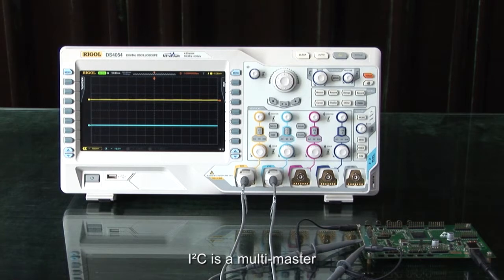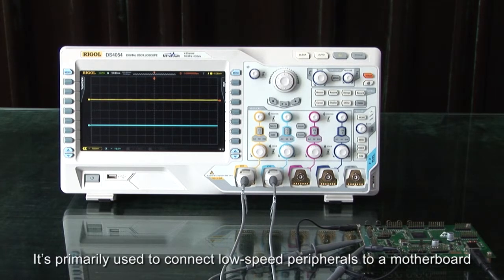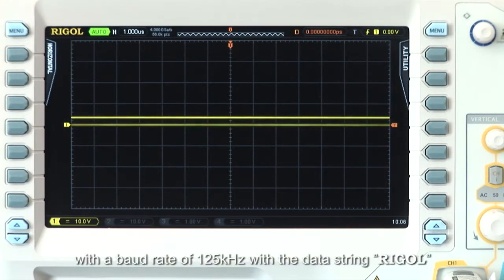I2C is a multi-master, single-ended serial communications bus invented by Philips. It's primarily used to connect low-speed peripherals to motherboards, embedded systems, cell phones, or other electronic devices. Here is an I2C signal with a baud rate of 125 kHz and the data string Rigol.